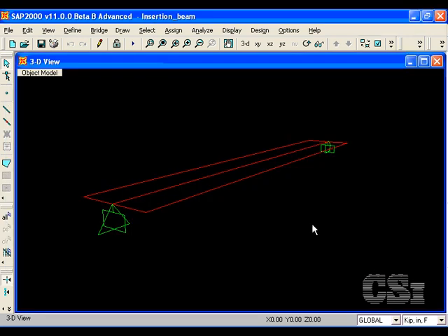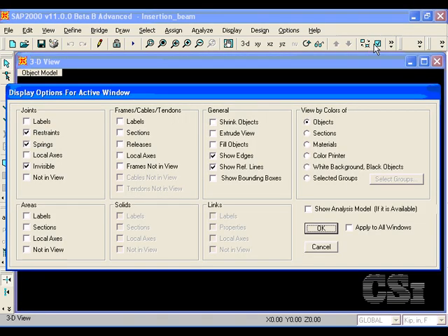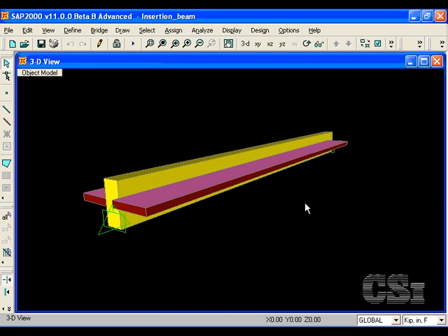When first drawn, the default settings are such that the slab and beam centroid all exist in the same plane. If we look at the model in an extruded view, we see that indeed the slab is located at the center line of the beam. However, in reality, we want the slab to be at the top of the beam so that it behaves as a flange.